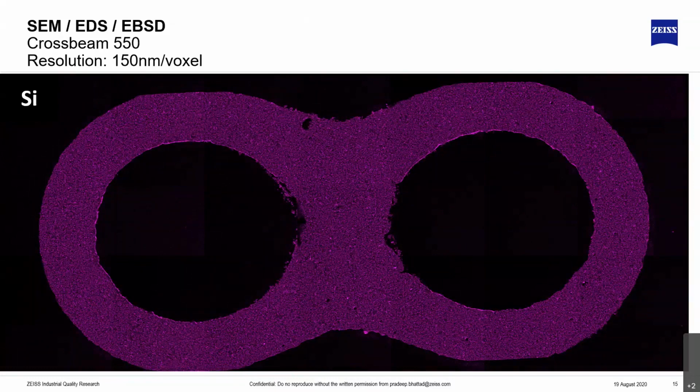So if, for example, I had a part from an Inconel build which was coming into this powder batch, and that gets included in the part, you'll start seeing signals of Inconel components. In this case, the part was very clean, so we didn't really see any impurities, but you can also start adding that information. Now I can also start looking at the mechanical properties by adding EBSD.